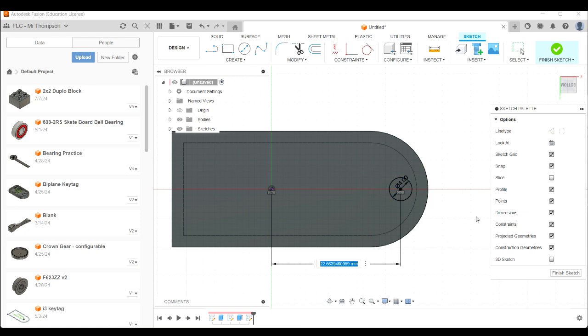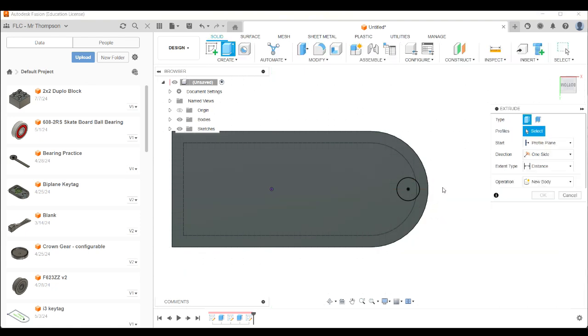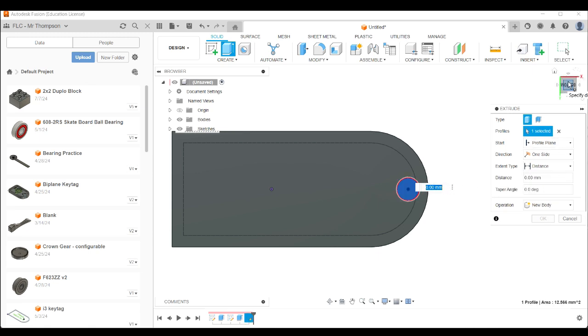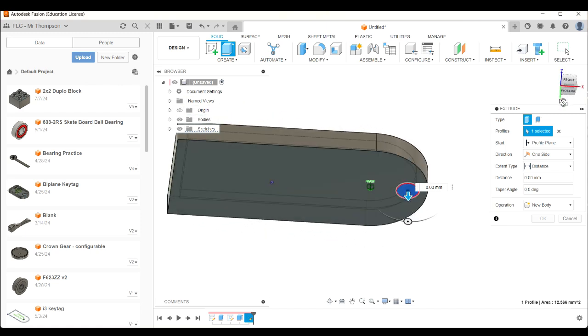So let's try a few things. Let's try 24 millimeters, enter. That looks a bit better, doesn't it? I think that's probably a good spot. So that's 4 millimeters all the way across. So that's probably 2 millimeters there. So now I'm going to press E for extrude, and I'm going to click there like that. And now the last time we did an extrude, we did an extrude where we're creating extra shape.